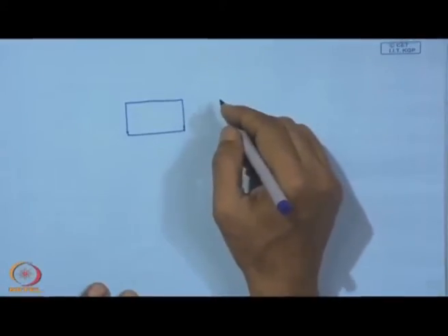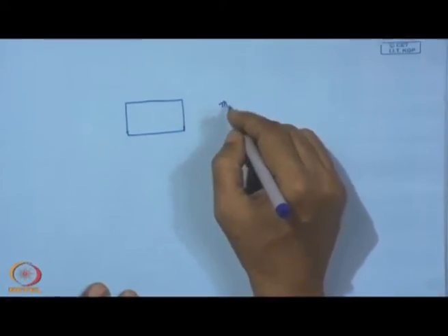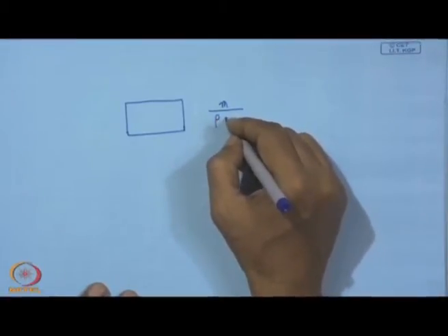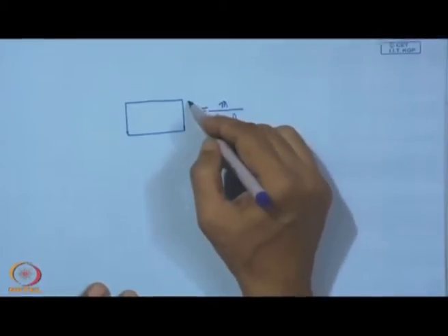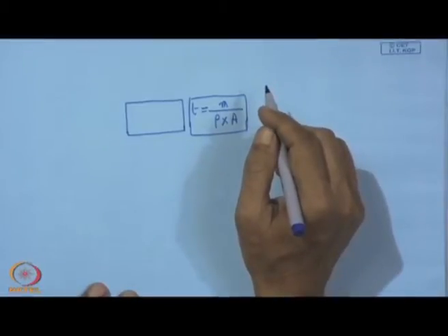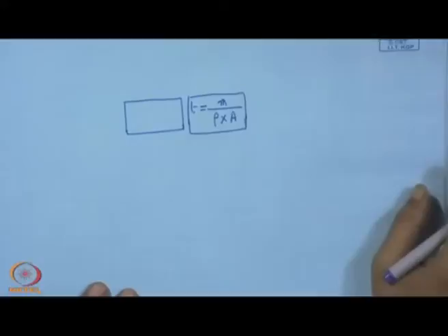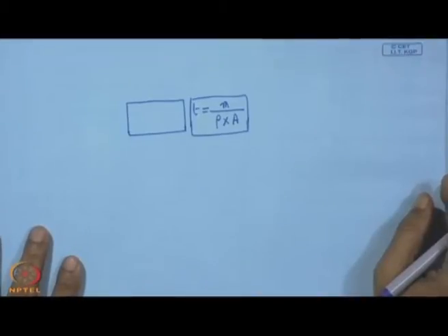and then because of this coating there will be some increase in mass or weight, which can be divided. That is the increase in mass divided by density and divided by the unit area. From that we get the average bulk thickness of the coating, but this is good for coating of those surfaces which are quite large and where we are more interested in the average value of the coating thickness rather than the coating thickness on a particular corner or particular geometry of a part.